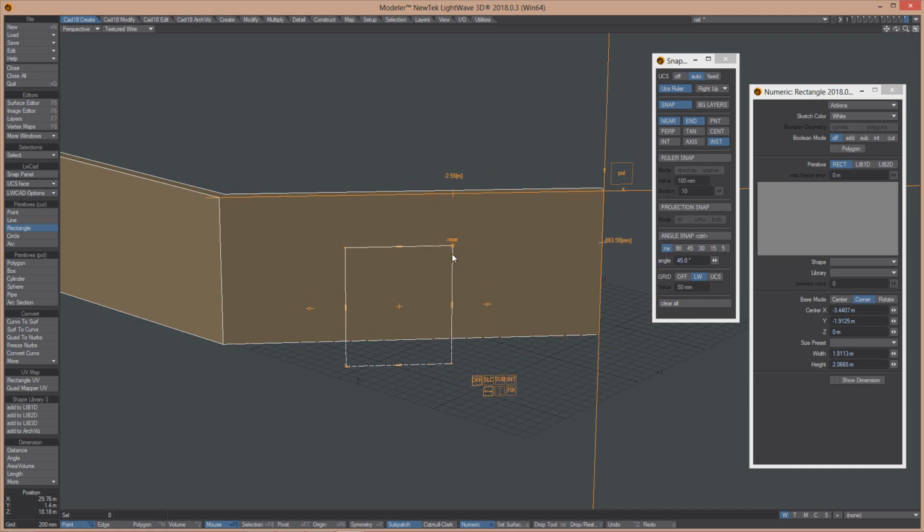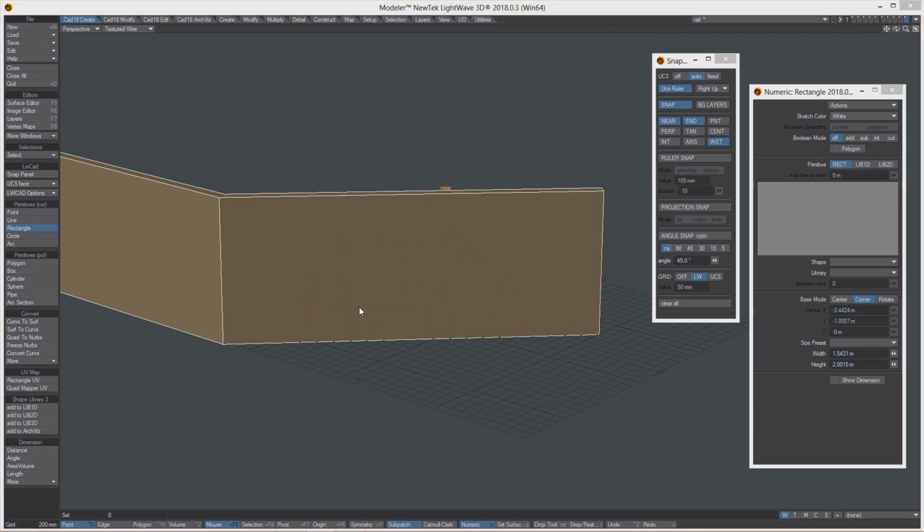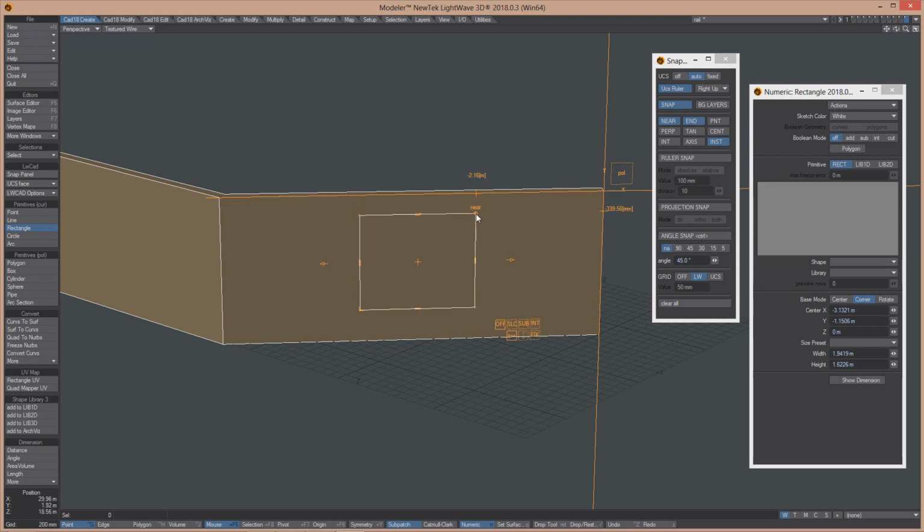So this helps precise placement on UCS, as I showed you previously with the window tool. And finally, for snapping, we have a new general snapping on-off button, so we can disable all snapping to geometry and then enable it back. This was again a request from users, so now you have it and you can use it.